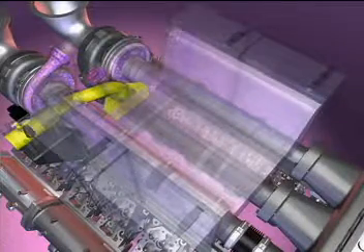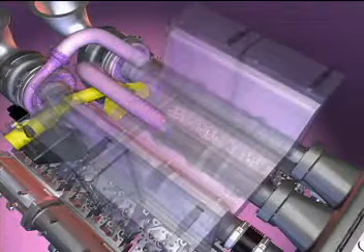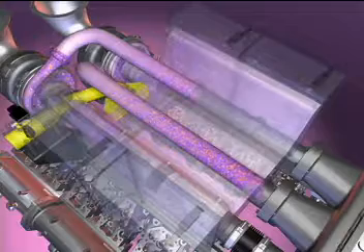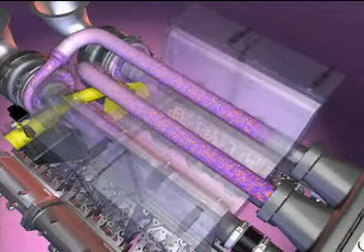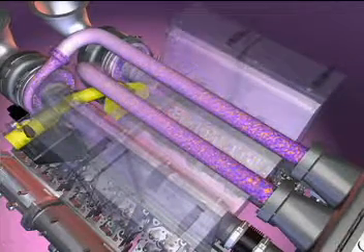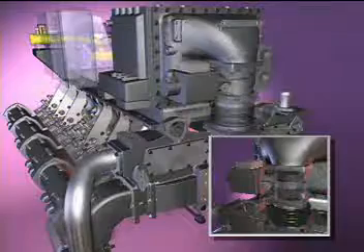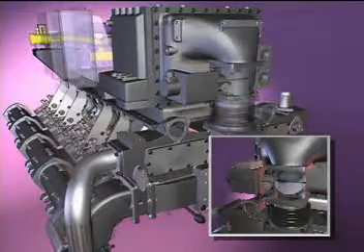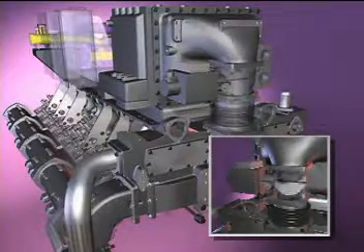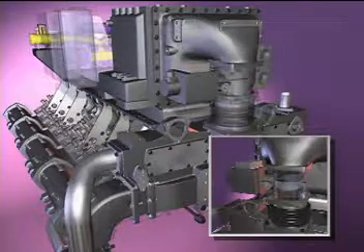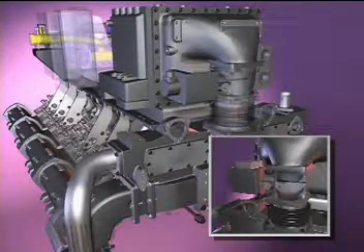To remove excess heat, the air-fuel mixture is sent through piping to the aftercooler. At this heat exchanger, the air-fuel mixture gives up heat to the coolant flowing through the unit. A throttle controls the amount of air-fuel mixture that flows from the aftercooler to the intake manifolds.